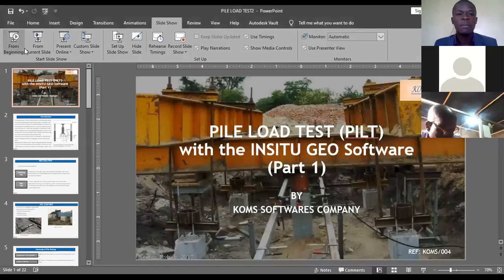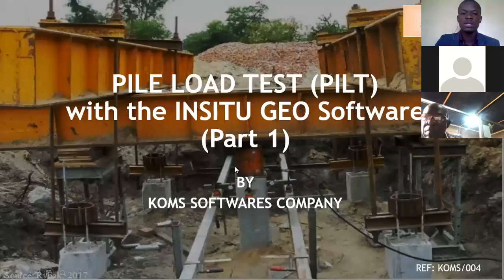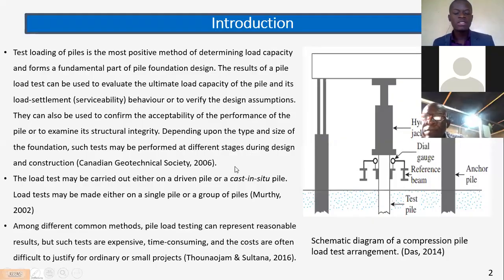The pile load test is the most positive method of getting the pile capacity, and it's an important part of pile foundation design. The results from this test are used to evaluate the ultimate load capacity of a pile, and also the load to settlement behavior, and to verify your design assumptions. It's also used to confirm the applicability of the pile performance, or to examine the structural integrity of a pile.